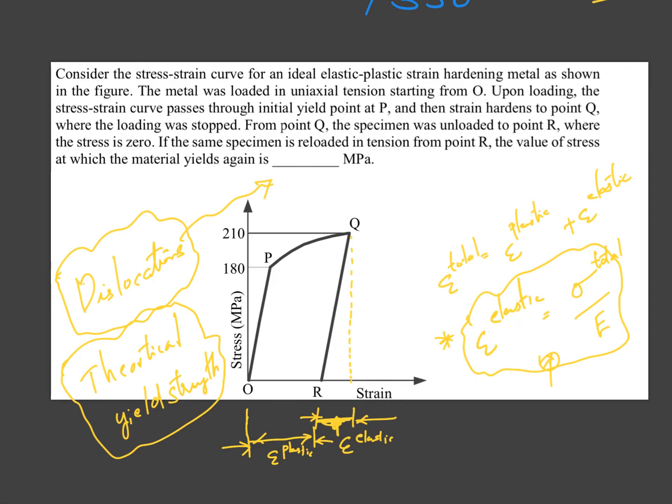What happens is, the yield strength of a material is related to the easiness with which the dislocations can move inside a material, or slip along a particular plane. So when you strain the material beyond this yield strength point, more and more dislocations get created, and because of the phenomenon called dislocation interaction, the mobility of the dislocations gets reduced, or their movement gets obstructed.